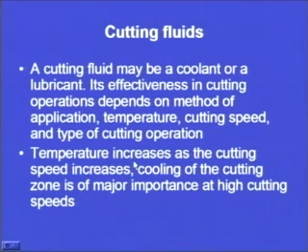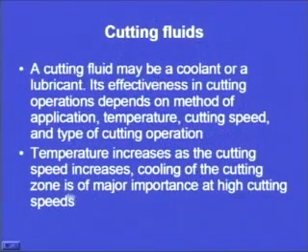Now, the temperature increases as the cutting speed increases. It is a general phenomenon that if we increase the cutting speed, then the temperature that is produced will increase. So, the cooling of the cutting zone is of major importance at high cutting speeds. If we are performing the machining operation at a high cutting speed, then the cooling of the cutting zone is more important as compared to machining at a lower cutting speed. Why? Because the temperature rise at high cutting speeds will be more as compared to the temperature rise at low cutting speeds.